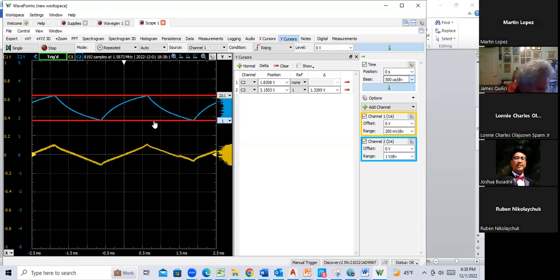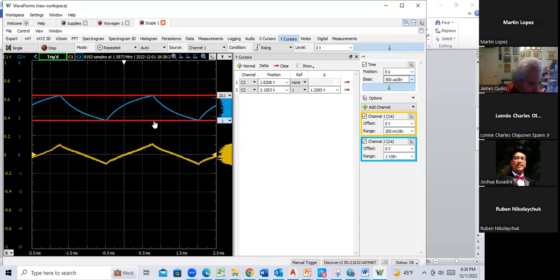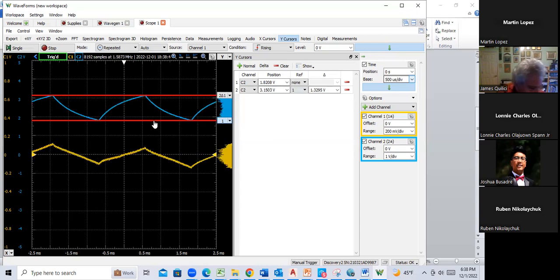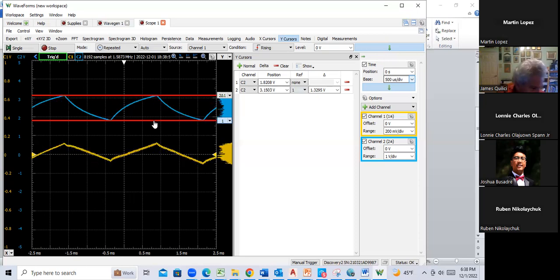And then they also give you a resistance spec, although it didn't ask us to measure it. So that's okay. But otherwise, in the SPICE simulations, we did a measurement. And you can comment on how accurate SPICE told you your input impedance was. Okay, it says present the final design in the form of a schematic diagram with all parts labeled, the one that you built. State the specifications for gain and output voltage swing along with the given specifications, and state the collector current and the value of VBB.